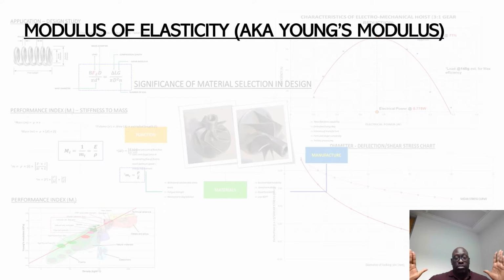extended. Okay. In that context, if we assume that for that given component there's no change in the sectional area profile, then the stress will also be directly proportional to the measure of strain that the material is being subjected to, or the amount of strain that the material is experiencing. Thus, sigma, which is the stress, is proportional to epsilon, which is the strain.